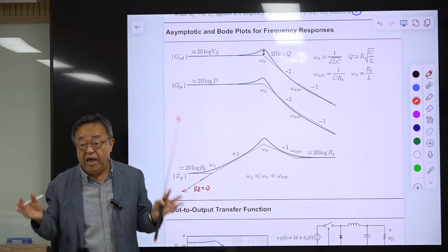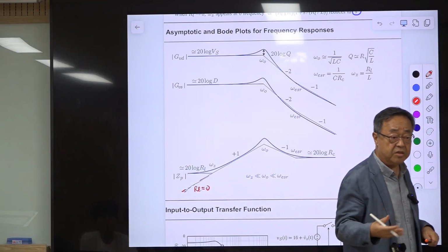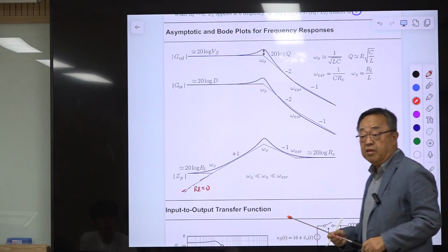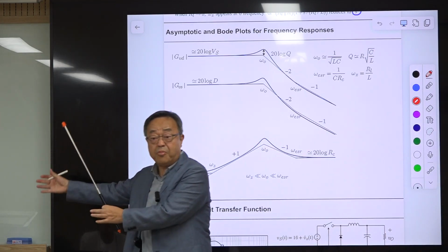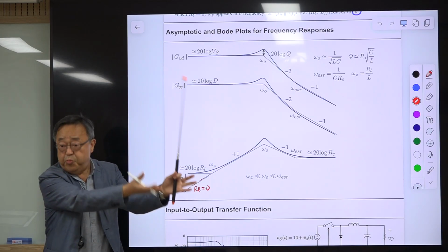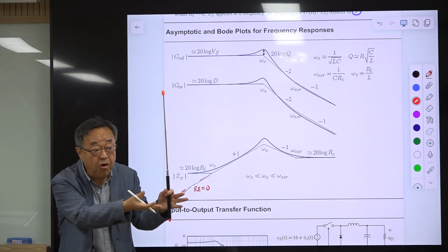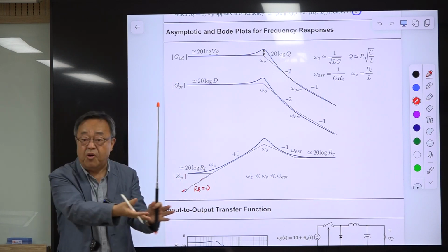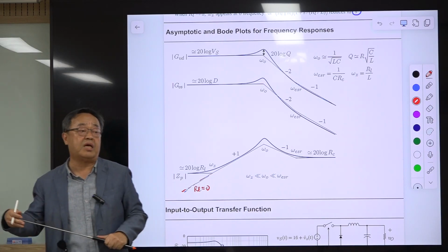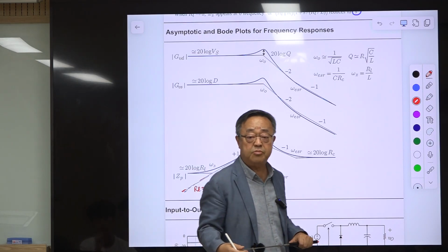Then you can apply all the techniques available for linear time-invariant systems, transfer functions and Laplace transformation, root locus, Nyquist, whatever. So you move the nonlinear, time-varying PWM converter into the regime of linear systems. Then you massage it with all the techniques developed for linear time-invariant systems. That is the objective of this small signal modeling.